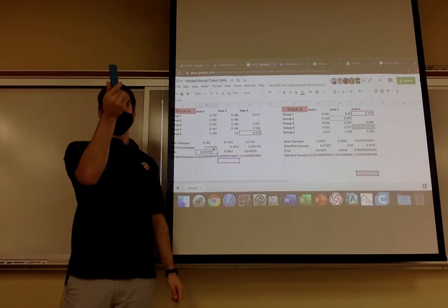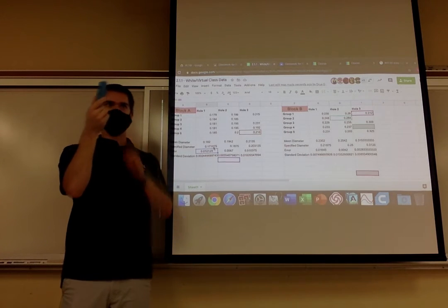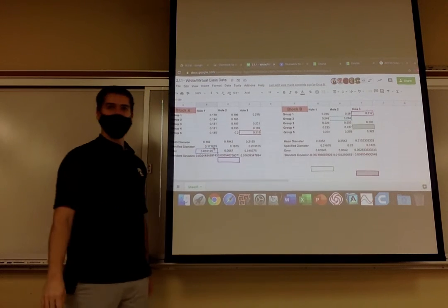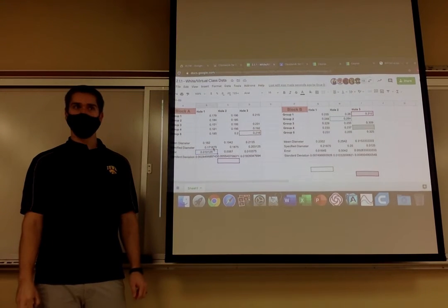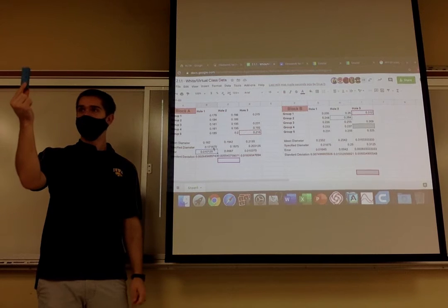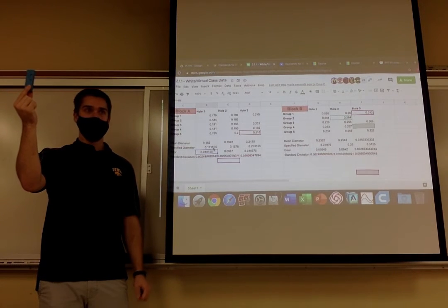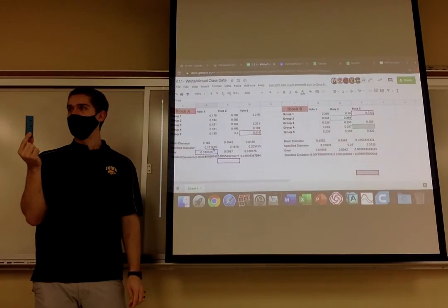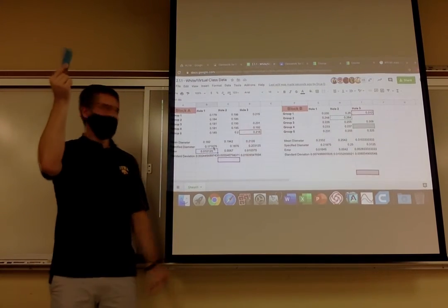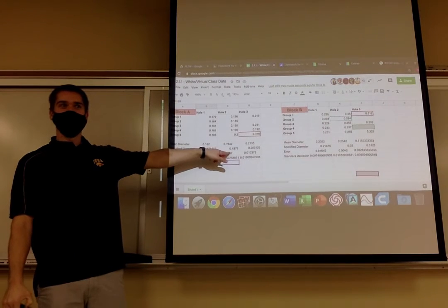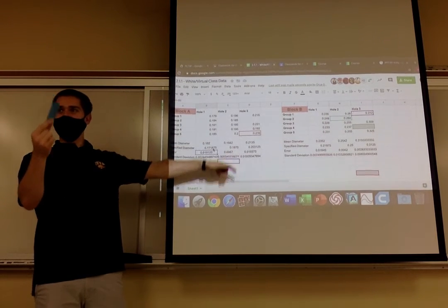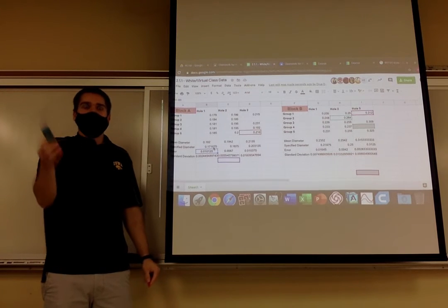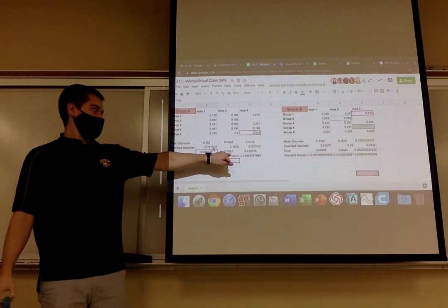What happens if this hole was for some port in an aircraft engine? And I said the tolerance is this dimension plus or minus 0.001, a thousandth of an inch. Does this pass? No. It's 6 times further away than what I'm allowing it to be. Again, as a kid's building block, I don't care about this. This hole could be just fine. But for an aircraft engine, a part on an automobile, a safety feature, this is unacceptable.